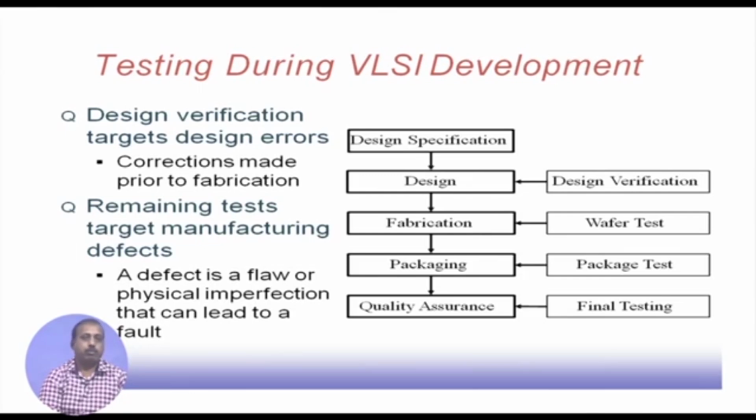If count becomes 15, then count will be reset to 0. That way we can write it in some hardware description language. Now, when this is converted into a counter design, it will possibly have 4 flip flops in it, and associated gates will realize the same functionality.